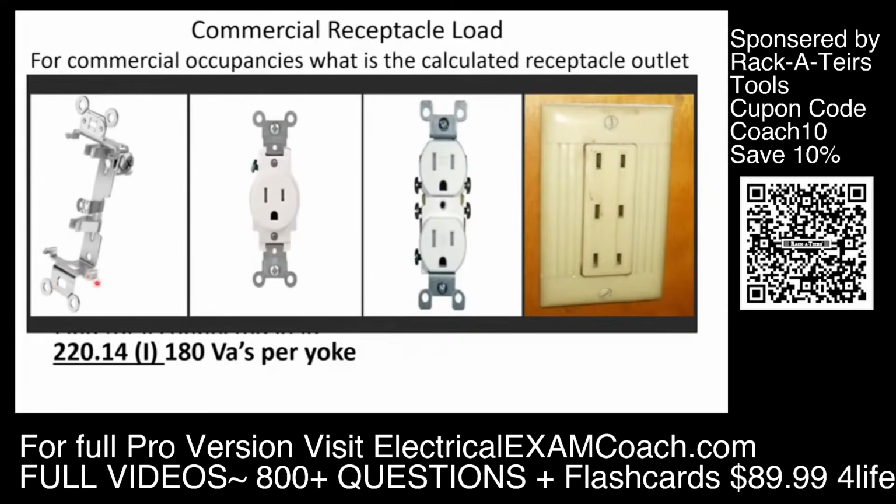What this code is stating is that whether we have a single, a duplex, or even this old school triplex here, each one of those would count as 180 VAs each. I like to think about it as each gang counting as 180 VAs. So if I have a single gang box, it's 180 VAs. If I have a 2 gang box and they're both containing receptacles on each side, it would count as 180 VAs per gang, and so on and so forth as you went to 3 and 4 gangs. Anytime you're dealing with a device strap, whether it has 1, 2, or 3 receptacles on it, it's 180 VAs per yoke.